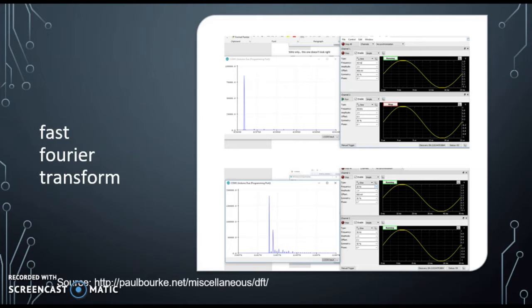As you can see here, we've used a wave generator to generate first a pure sine wave at 50 Hz and then used an Arduino to run an FFT on the signal. The resulting plot has one large peak associated with just that frequency. In the second plot down here, we've combined a 50 Hz sine wave and a 20 Hz sine wave. And in the resulting plot in the frequency domain, you can see multiple peaks at different frequencies.